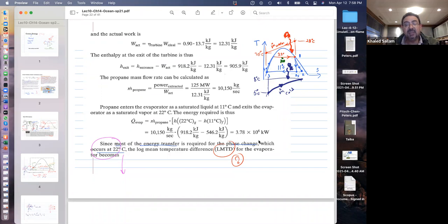Now this is being carried out by the warm water. So if you want to calculate m dot warm water, you would say that Q, and you can see how big it is. For 125 megawatt, he's pulling 3 megawatt. For 125 megawatt electricity, he needs to pull how much heat? 3 megawatt. Why? Efficiency, we have a spoiler alert, right? The efficiency is 3%. That's why. So you need to think, I need 30 times more. For 3% efficiency, you need 30 times more heat than what you're going to produce. Right?